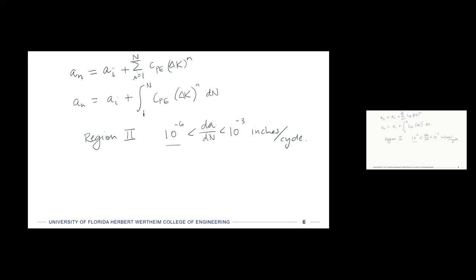The book gives a lot of thresholds for this, about like, what is the minimum delta K sensitivity at which you start to be able to use Paris law, right? What's the lowest number of cycles or lowest stress or whatever to be able to use Paris law? So they give some threshold values there. They call it like delta K threshold.